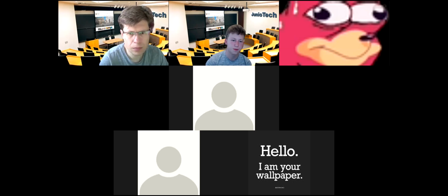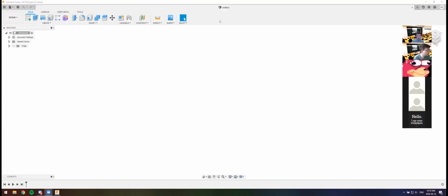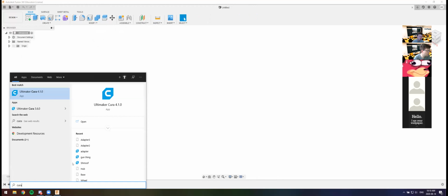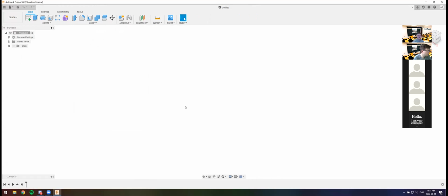So the main thing we're going to do then is we can talk about that for the starters, and then we'll see what we have time for afterwards. So when you're modeling anything, you're still going to be starting up here in Fusion, all right? And you're going to create some kind of object, and then you're going to bring it into another software called Cura. If you don't have it installed yet, don't really worry. You can install it right now or after this class. Just make sure to pay extra attention while I'm showing. But basically, Cura is software made by Ultimaker, which allows you to take these files from Fusion and then convert it into some kind of code that a printer will understand. Right?